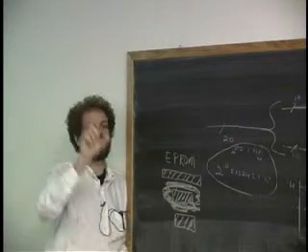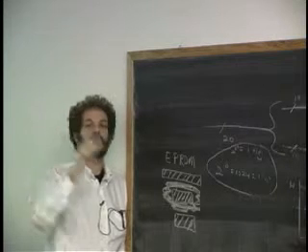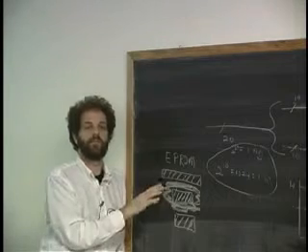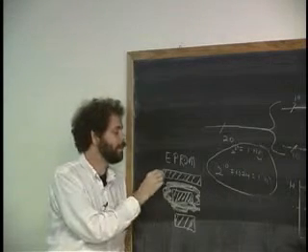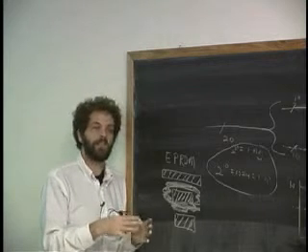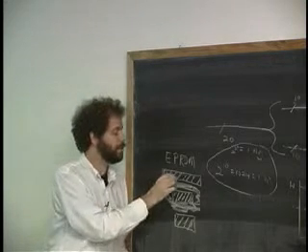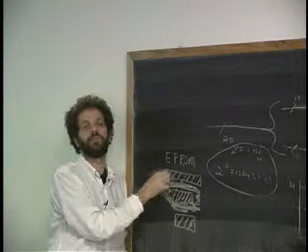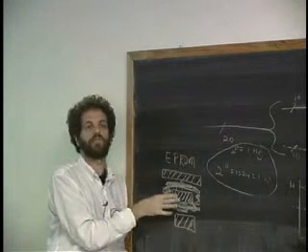Okay? But you need a lot of volts here. And ordinarily, when you walk around with a chip like that, you don't have 20 volts to get to the other side. So the chip will last for 20 years if you don't put high voltage on it. But if you put this EEPROM inside of an EEPROM programmer, which has 20 volts on it, it can still read or write, store or take away charge from this guy in the middle. And as soon as you take away the 20 volts, it lasts forever.